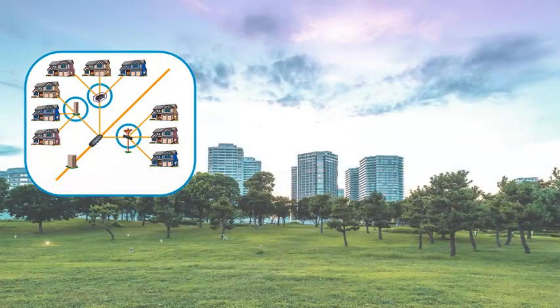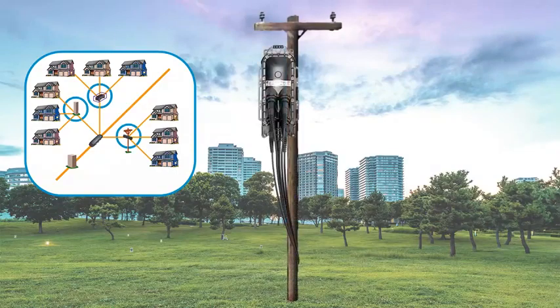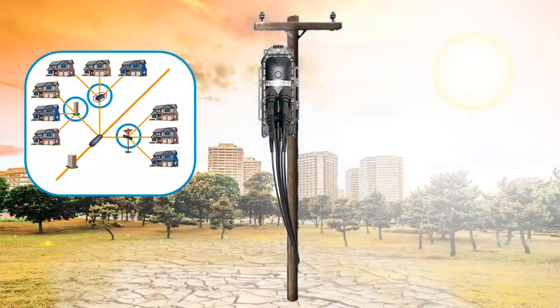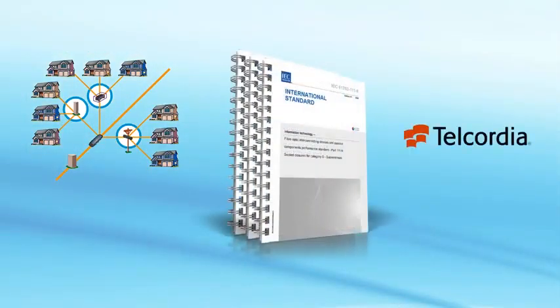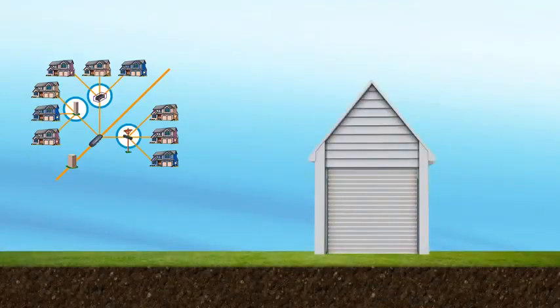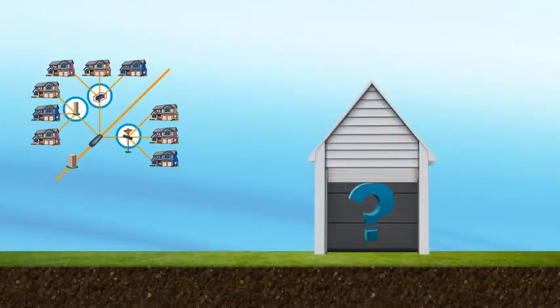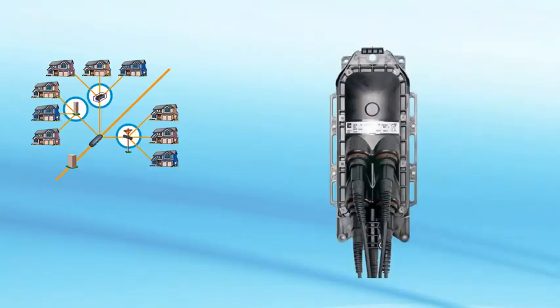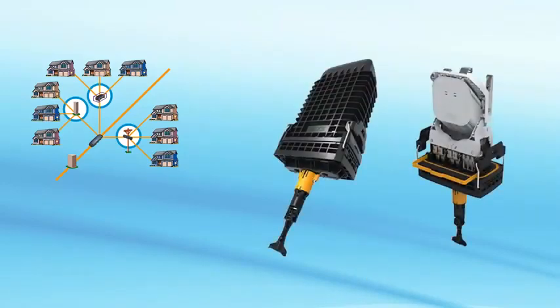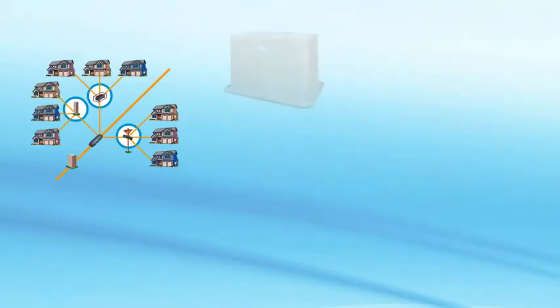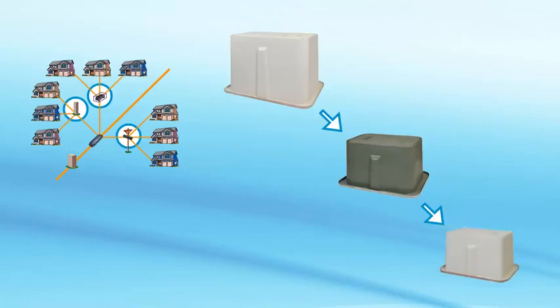For outside applications, the drop cable solution has to withstand the rigors of extreme climate change, moisture, and harmful UV with fully compliant IEC and Telcordia-approved connectors. For indoor drop applications, the solution has to meet very different performance and labor requirements. Utilizing plug-and-play solutions like the Multiport Service Terminal or MST with hardened adapters eliminates the need for splicing at the fiber access terminal, which means the handholds or pedestals that store the terminals can be much smaller and therefore can reduce materials costs as well as simplify installation.